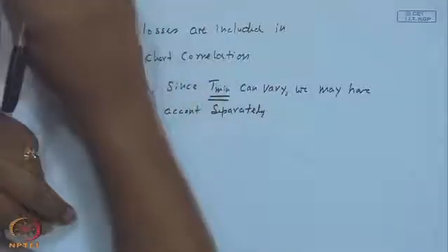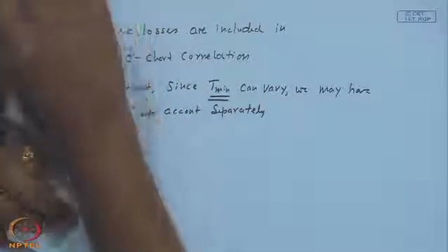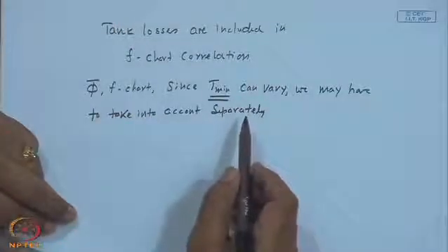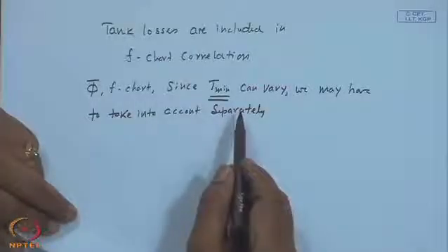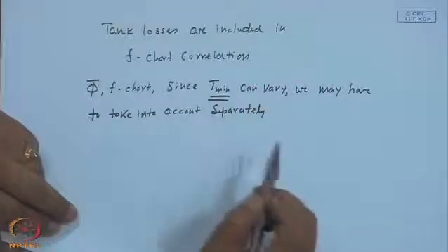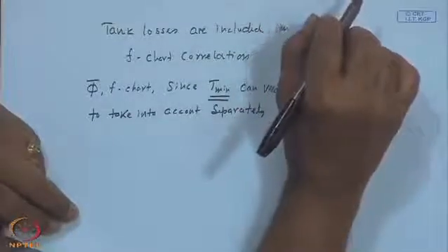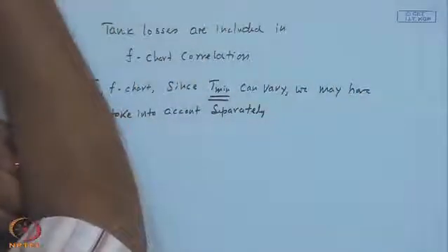So, once again we include heat exchanger. Indeed, in the F chart method also, though losses in the pipes and tanks are not mentioned, heat exchanger size has been mentioned, and if the heat exchanger size is not the standard size, you correct the variable y as y c by y, some exponential function. So, the heat exchanger is there in the F chart method also.